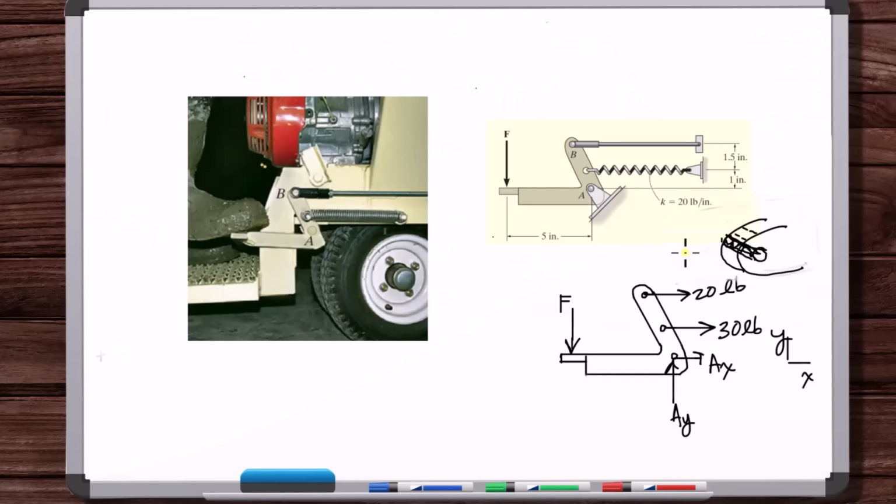The volume under the pressure curve is this load here, 20 pounds in that pin, or 30 pounds here. And what happens is if you have a distributed load that's symmetric with respect to that center plane of symmetry, and let's say this is a pressure curve, there are no components of the pressure that are perpendicular to that center plane. So the distributed load is symmetric with respect to the center plane, and there are no components of that pressure perpendicular to the center plane. Then the resultant force is going to lie in the center plane.